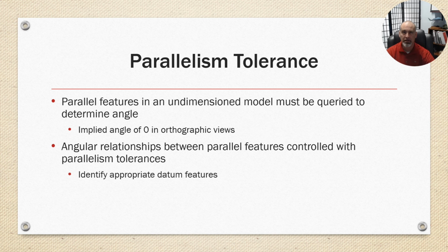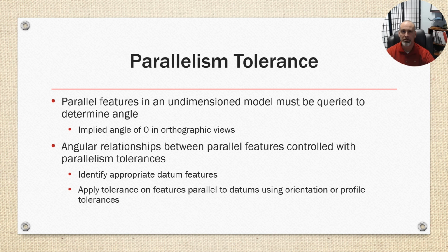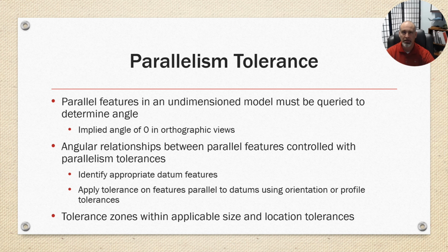Identify appropriate datum features. Apply the tolerance on features parallel to the datums using orientation or profile tolerances. Tolerance zones within applicable size and location tolerances.